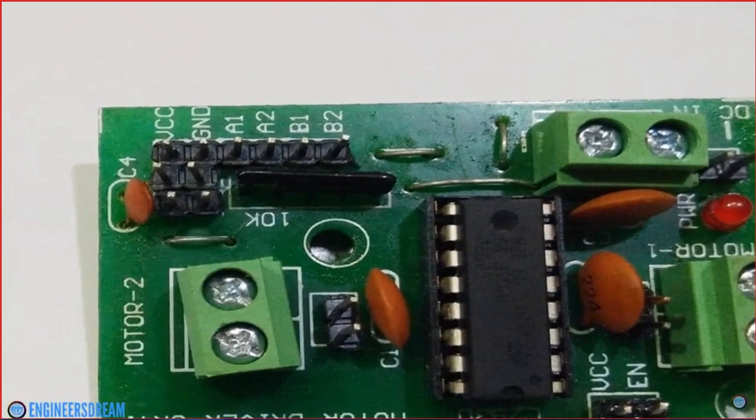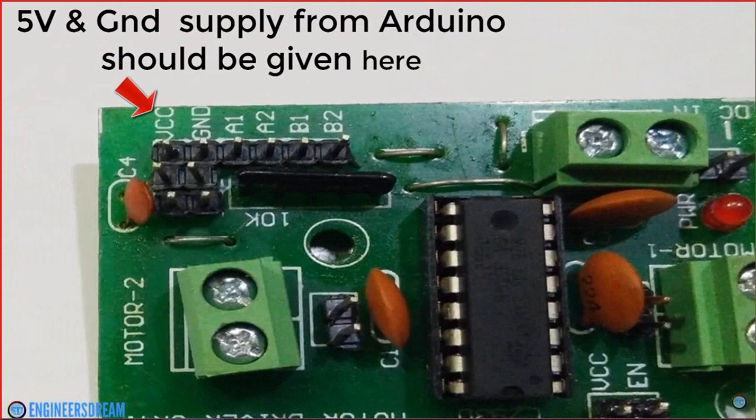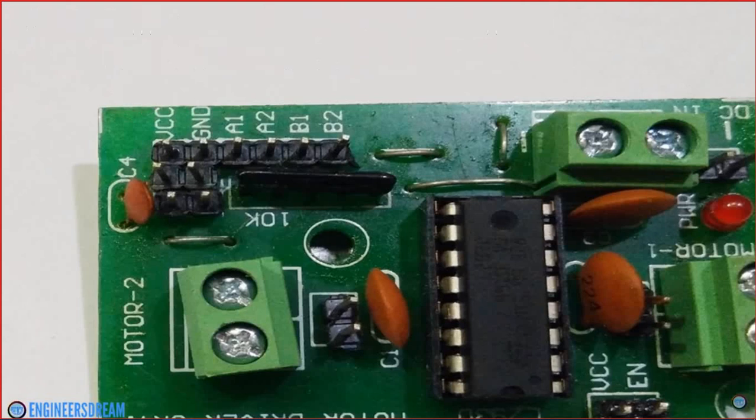Now, if you look closely, there are 2 more pins for VCC and ground. At the VCC pin, we had to provide a supply of 5 volts from the Arduino. That is, I had to supply power from the 5 volt pin of the Arduino to this VCC pin. And I also had to connect 1 ground pin of the Arduino to the ground pin of the motor driver.